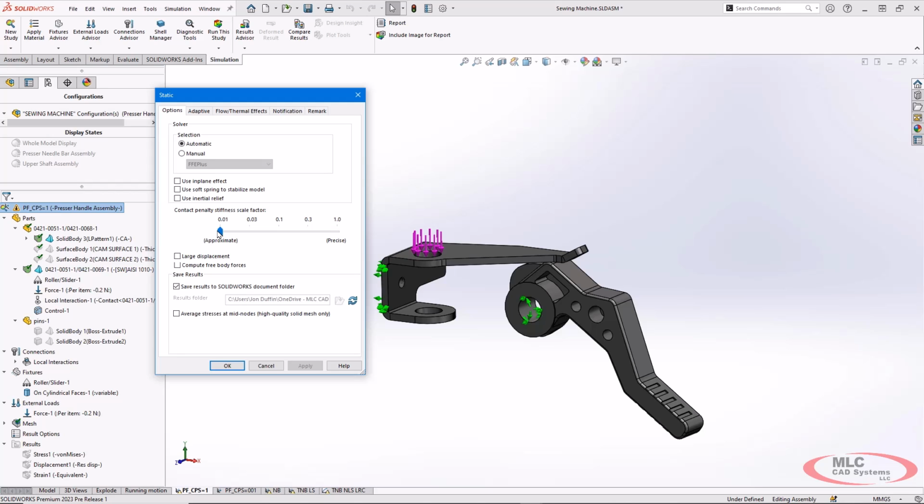So this can be a great tool, hey, as you're setting up your first pass analysis, same reason you use a coarse mesh to begin with, or even go to a draft quality mesh. Hey, you need to evaluate your results. You need to go through a few iterations before you run your first pass. So a great tool to be able to get to that endpoint quicker. So a cool option, pretty straightforward to use.